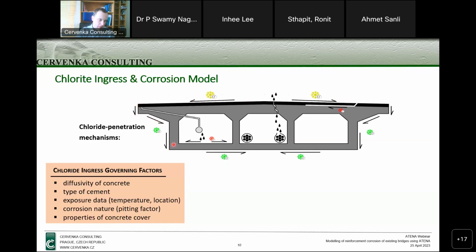However, some spillage can go on also from the bottom and left and right side, as well as in some cases it needs to account for some potential emergency scenarios, which may be some leak through the drainage, or leak to the duct of the prestressing cables shown in here, and leak from the drainage system shown in here, or for example leak of the chlorides from under the road finish, and then it can directly penetrate to the load bearing structure.